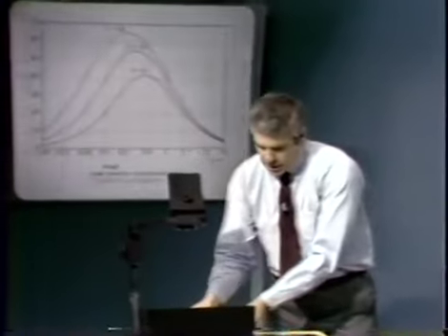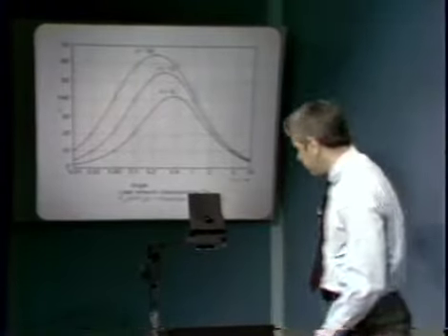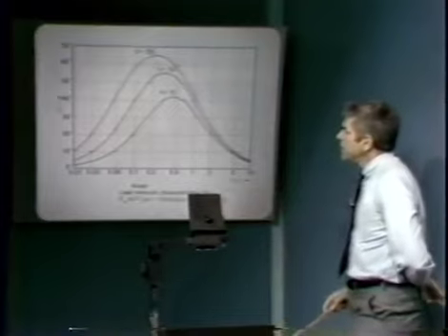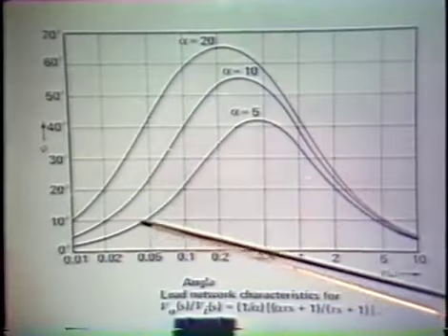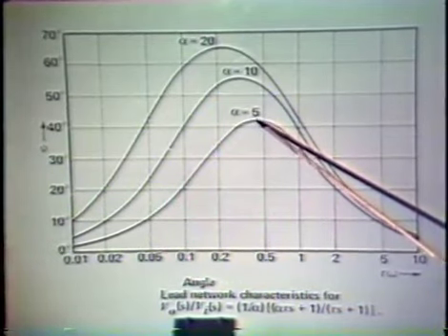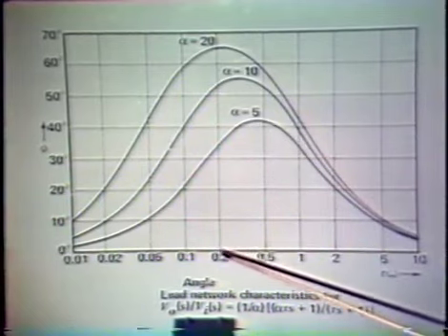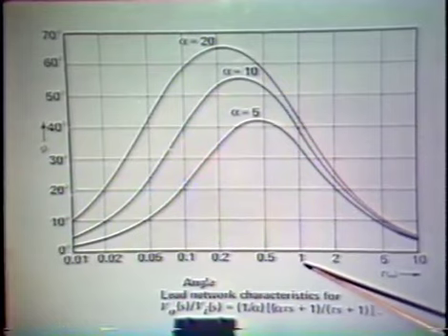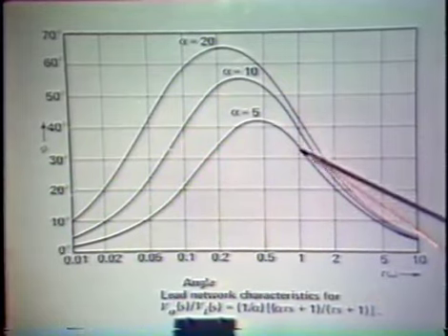And here is the angle associated with the lead type transfer function. We notice that even for a relatively small value of alpha, we get a positive phase shift whose maximum value actually occurs at the geometric mean between the 0 and the pole location. Remember that all of our networks were normalized to unity for the location of the pole, so all of our networks have the pole at this frequency.